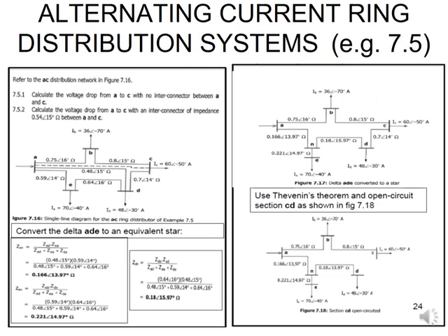But in this case, you've done your delta to star, it was not even your interconnector. And secondly, you had an additional load in here. So you are not working exactly with the same point that you've done a conversion in. In other words, you didn't touch D and C in all of your calculations when you did your conversion. Okay, so that's why you are able to open circuit that CD point. So then they open circuit the CD point.